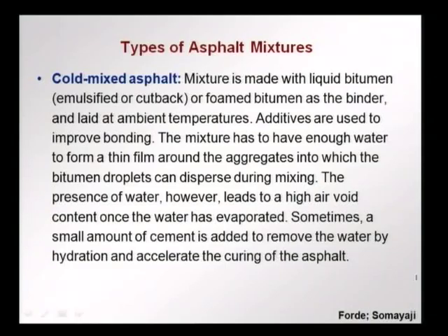However, since there is a lot of water in the cold mix asphalt, as the water evaporates it leaves behind air voids. So, there is a relatively high air void content in the cold mixed asphalt once the water has evaporated and the compaction is complete.